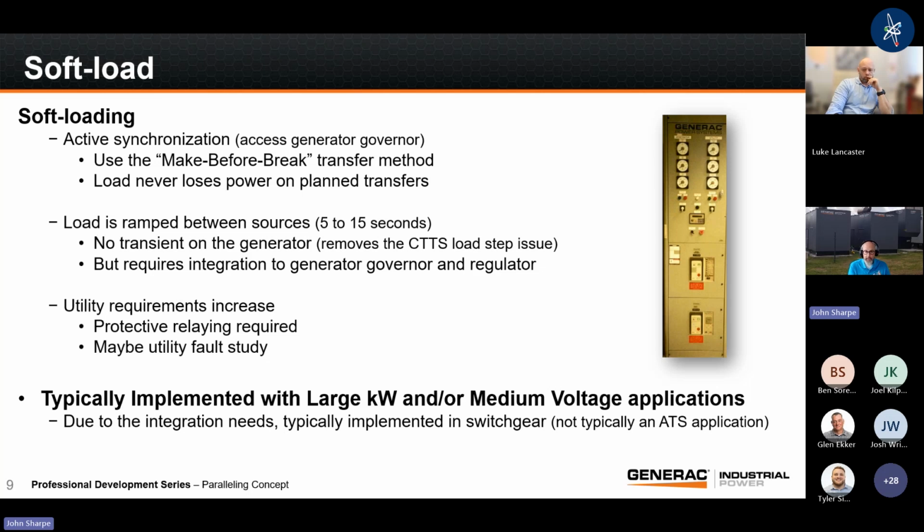Also, if you were doing some sort of testing or a curtailment program, demand response, anything like that, I'm starting the generator and I want to transition to the generator. Same, right? I've got 300, 500 kW of load sitting on the utility and I'm going to immediately put that onto the generator. The generator is going to get a very large block load.